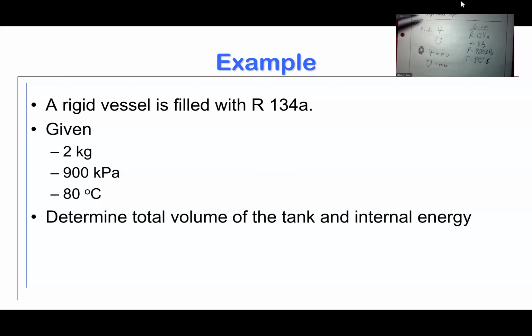So what I've just done here is I said, okay, what am I looking for? All right, well, what tools, relationships, laws do I have that find it? Well, I have table properties, but the properties aren't going to give me total volume or total internal energy. I need an equation that converts the specific volume and the specific internal energy given into the total volume and total internal energy I need. So now I've got expressions, right?